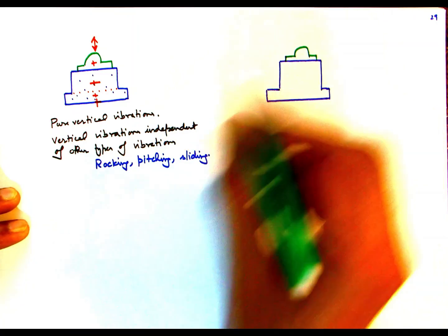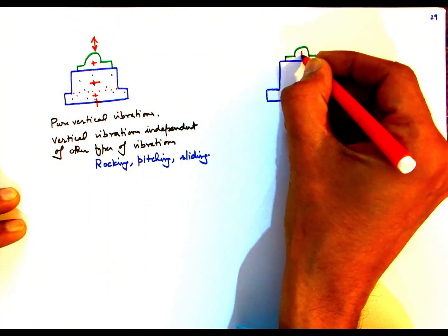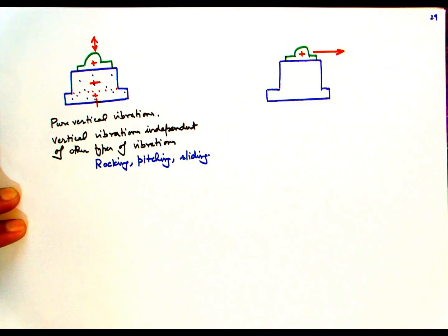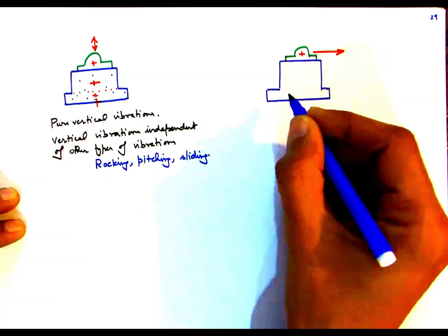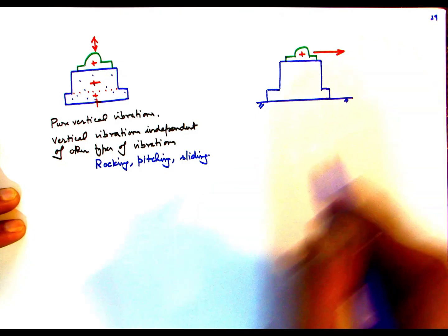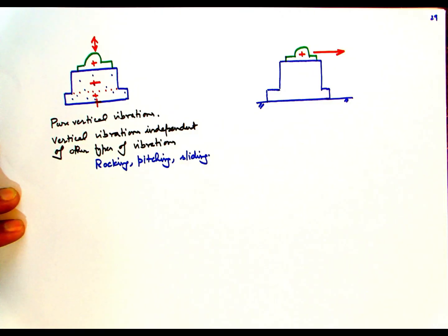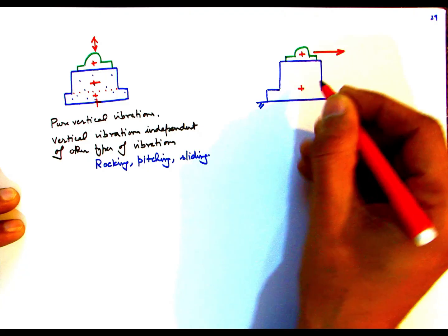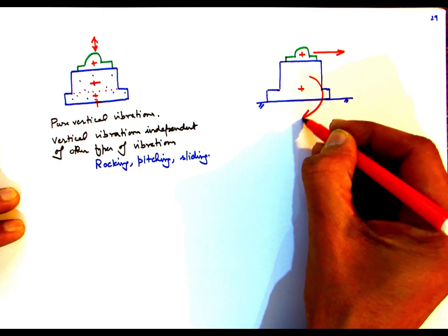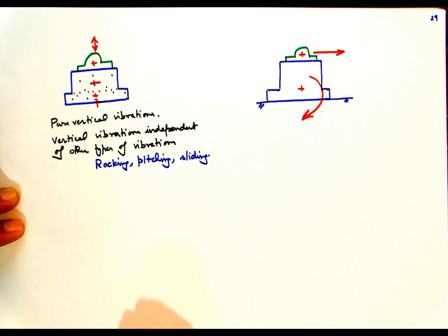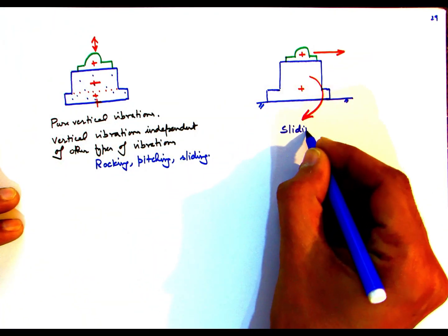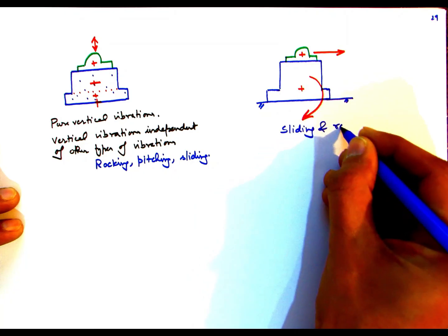Let's say we have the machine resting on the top of a block type foundation, but it's generating horizontal forces, a reciprocating type machine reciprocating in the horizontal direction, then it will not just induce sliding, because the horizontal force is acting at some height above the center of gravity of the entire system, so there would be a bending moment also associated.